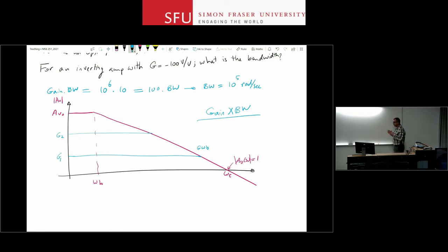So that's the op-amp while it's still behaving as a linear element. It's just a linear element, it's single pole. That pole makes it behave like a low-pass circuit, but things are still linear. There is a speed limitation, as we just saw. If you go very high in frequency, the amplitude of the gain will drop. But we can still deal with it using linear system analysis.